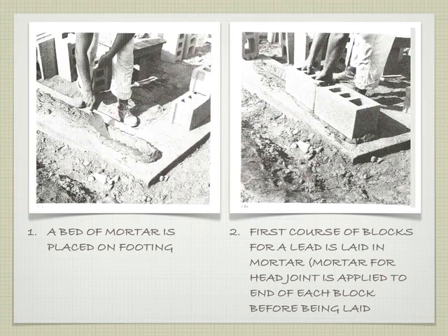let me try to illustrate this a little bit better. Here's my footing. I put my mortar down on my footing. I take this block and I put it down. I'm ready to attach the next block in series. This one's much heavier. I already have the mortar on the ground, but I apply the mortar on the head of this block so that when I put it into place, the mortar's already on this surface and can start to tie these two pieces together. Okay?